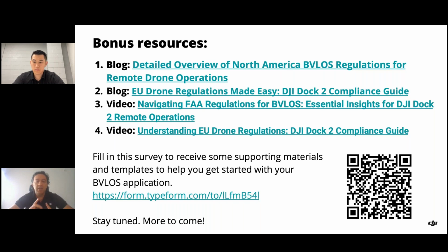The requirement is that they have to cover 2 statute miles around the site, and any of them could lose sight at any point, with the other one covering and achieving the task. So essentially, you're having more than one visual observer, and certainly you can use daisy chaining, not to extend too much, but at least to cover the base requirement of two statute miles. So this is important to keep in mind: you can have more than one visual observer.